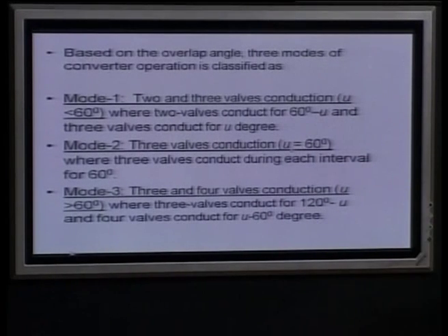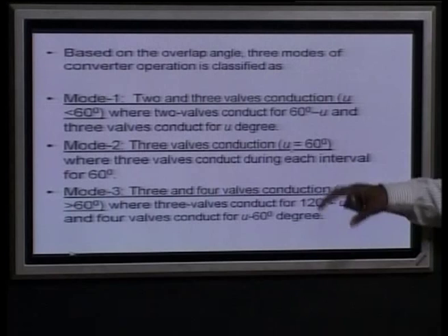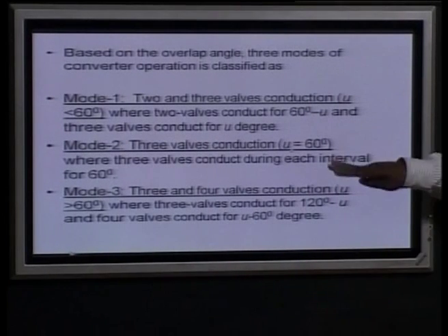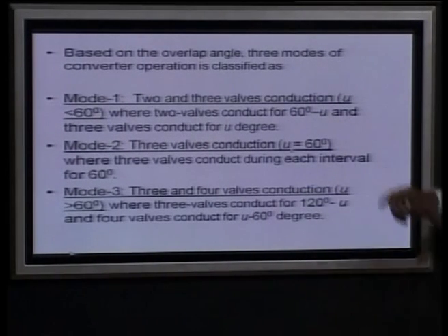So we also have to analyze this case and see what the problems will be during this. We will see that the extra harmonic components will be tremendously high, and the jumps in the voltages of the valves will also be very high. First we have to take case 1 here.